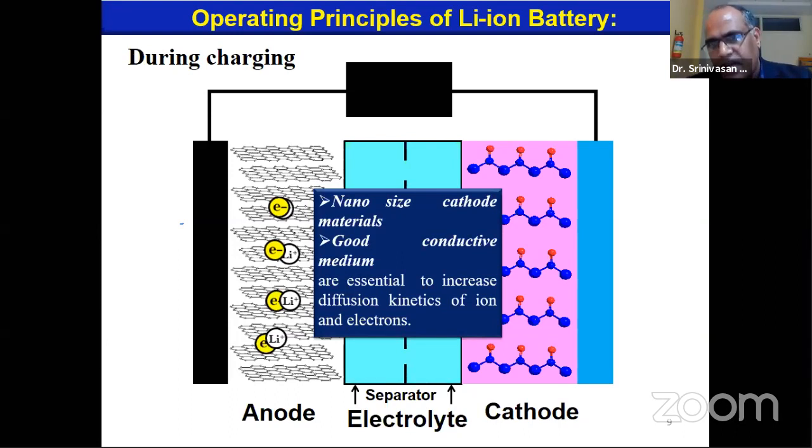And considering the advantage of the supercapacitor, look at the lead acid battery. People are using lead acid battery powered e-rickshaws in Varanasi. It is very popular. But the problem is it lasts only 500 cycles. And whenever there is acceleration or a slope, this lead acid battery is unable to deliver the power. When you integrate the supercapacitor into the lead acid battery, whenever there is a high power requirement, the power runs from the supercapacitor, and you are not abusing your lead acid battery. By integrating the supercapacitor into the lead acid battery, you are increasing its lifetime. For that kind of application, the supercapacitor is useful.